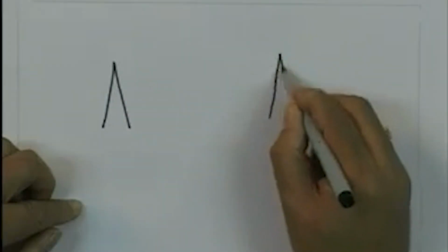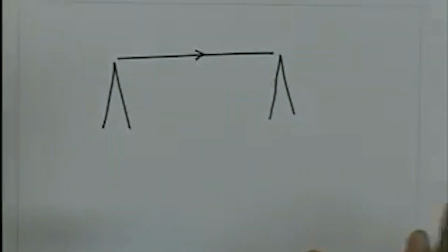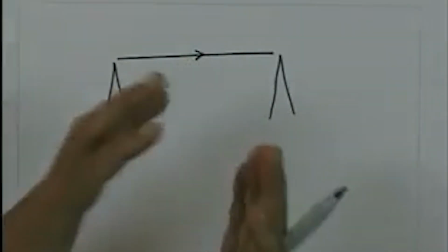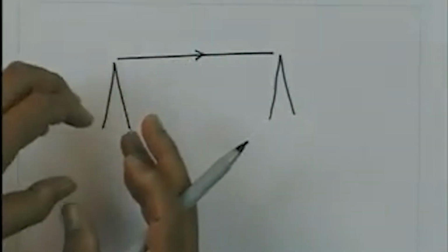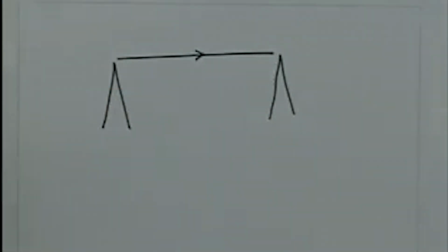Let us say I want to establish communication between 2 points, as we do, for example, in microwave towers which we see around us. So, I have a microwave tower here, I have a microwave tower here, and the interest is essentially to send the power from this location to this location with as minimal loss as possible. In this case, I would prefer to have an antenna which will be highly directional. That means this antenna should put power only in this direction and should not give the power in any other direction.